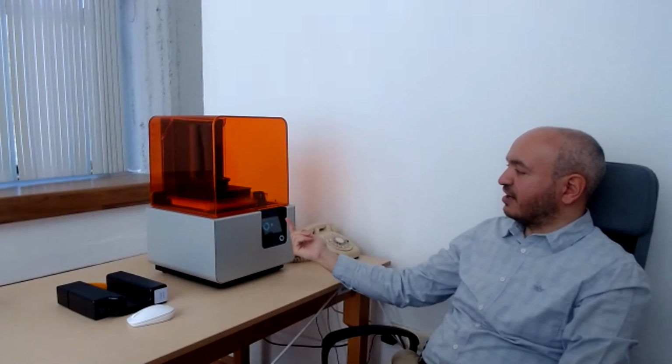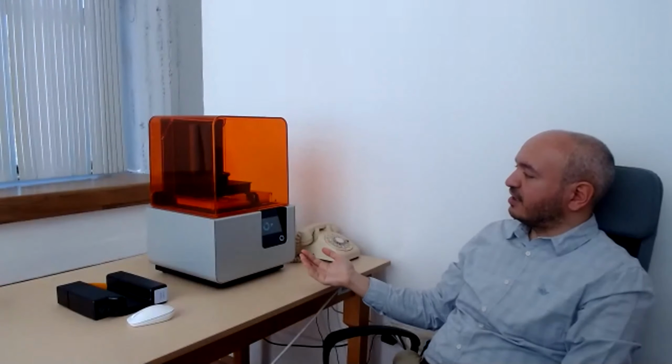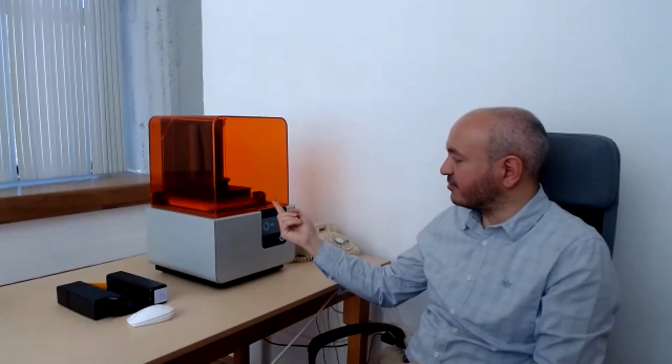And you see some steps are performed at each layer. Right now, we have a laser underneath and it is curing. After each layer is completed, we have a kind of sweeper. It sweeps the photopolymers on the table so that there are no bubbles around and the part does not stick to the table. After sweeping, it goes up and then goes down. And the next layer is now being cured with the help of the laser underneath. This laser is scanning the whole slice and trying to solidify this liquid material, this liquid resin.